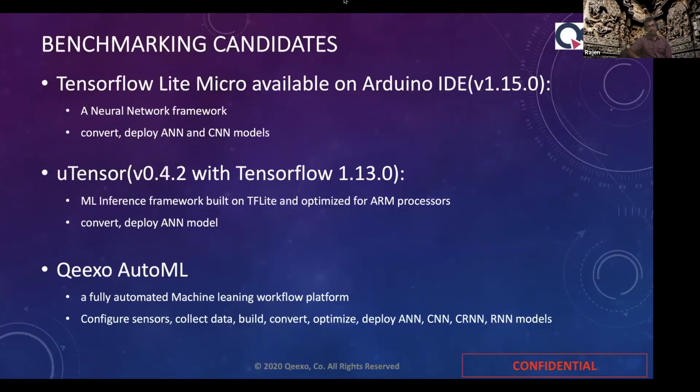In order to do that, we will be taking three benchmarking candidates. We will be taking three frameworks which are available. The first one is TensorFlow Lite Micro, and we will be using TensorFlow Lite Micro through the Arduino IDE because it allows us to ingest the TensorFlow Lite developed model, convert it to an Arduino sketch, and then deploy it onto the Arduino hardware.